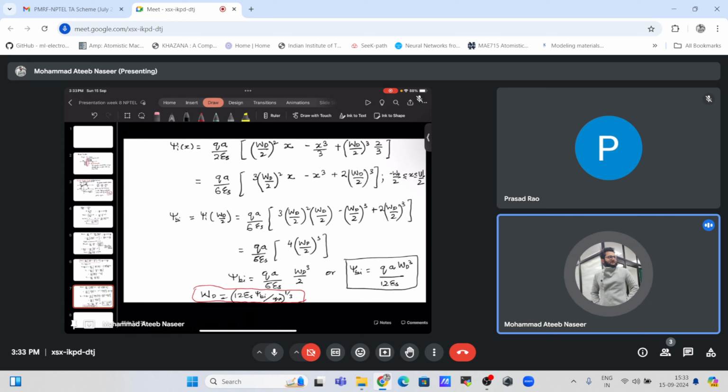The case can be that both the depletion widths are different, and in that case we will have a different built-in potential, which will be a function of WDP and WDN, and the electric field will also be a function of WDN and WDP. So this was a simple case where we solved for a real metallurgical interface, where the transition was not abrupt but linear.